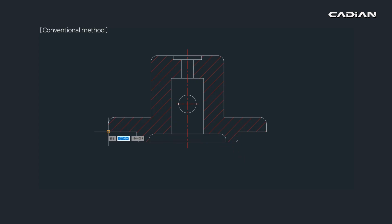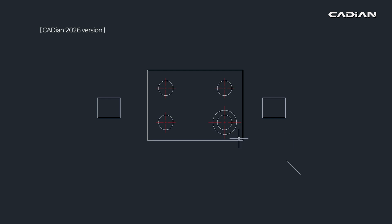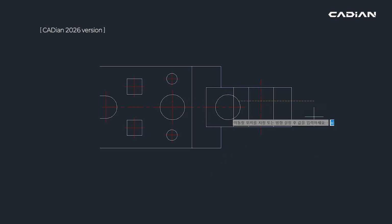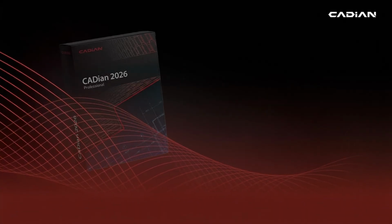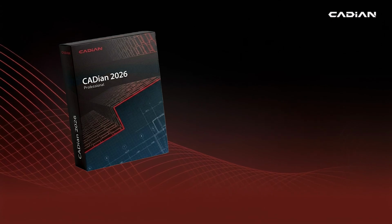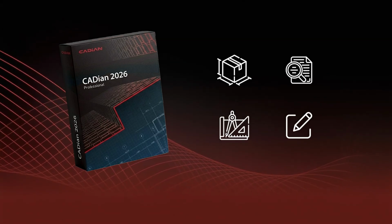What consumes the most time in your drafting workflow? Usually it's dimensioning, modifying, and repetitive tasks. CADian 2026 has tackled these exact pain points. You can now place dimensions and generate centerlines in a single step and execute copy, move, trim, and offset commands faster than ever. Let's walk through the key new features in CADian 2026, covering dimensions, detail views, drafting, and modification.